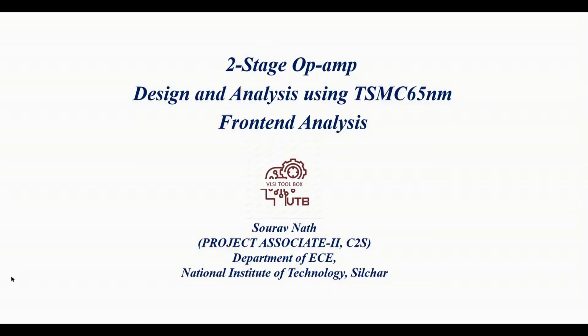Today I will be showing you how to design a two-stage op-amp and do the corresponding analysis using TSMC65nm technology. This video is basically a front-end analysis. I will be showing you back-end analysis in the upcoming videos. So let's start designing the op-amp.